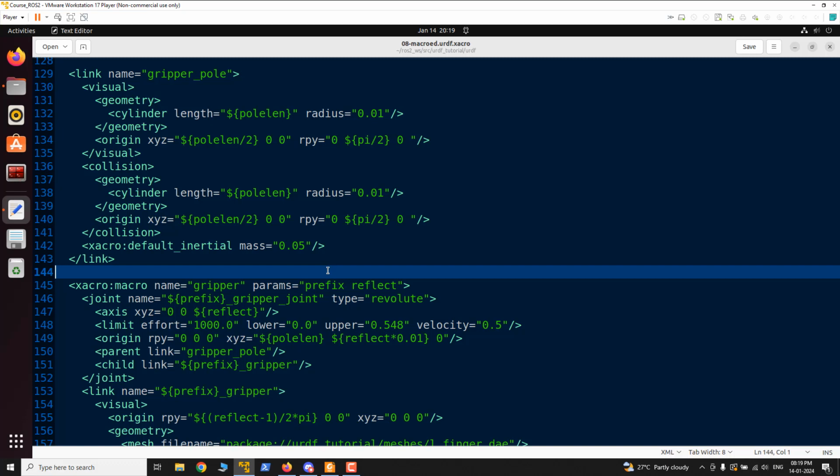While working on the URDF, currently we are working on a text editor in order to write the URDF. So we have VS Code. That's what I'm currently using. It is good for visualizing at the same time. For example, currently what we are doing is modifying the Xacro file or URDF file, and then running the launch file to visualize it in RViz. But if you want to see the changes in real time, what I'm saying is, whenever you change the URDF, you can see the changes on the right side of the VS Code window. Which is very useful, because you can quickly do the modification.